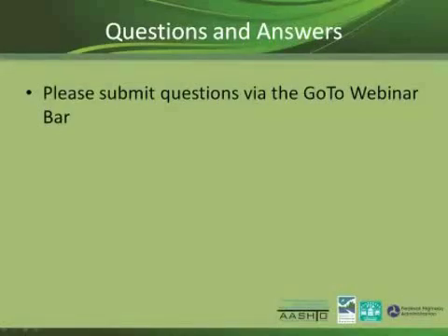So another question was, where do the pollutants go within the pavement, and what do you do with them? Our thinking, when we've looked at it over time, is that we see enough reduction in porosity to account for all of the observed water quality benefits. And you're getting accumulation of more than just stormwater stuff, because during dry periods there's dust fall, and particles accumulate on the road and fall in there. So what we're seeing is a very slow decrease in porosity over time as this stuff accumulates.